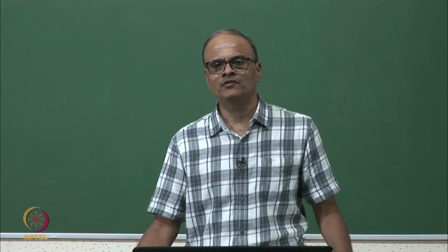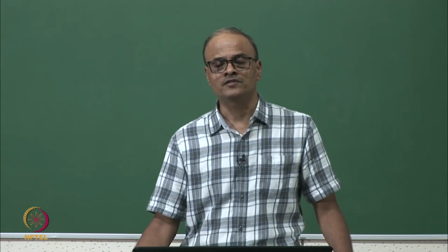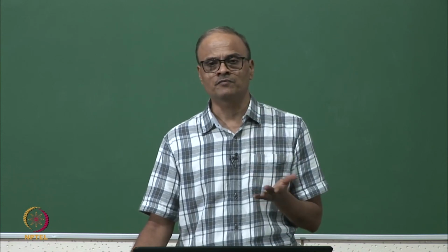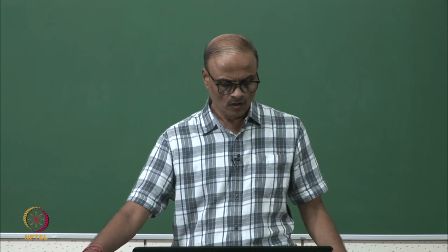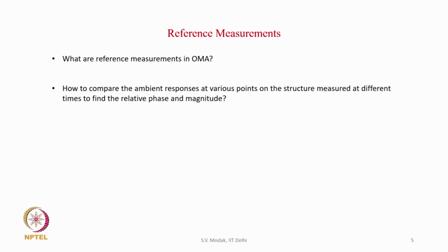One of the differences between the operational analysis and the experimental analysis is the fact that in operational analysis reference measurements are taken. So, let us try to understand what reference measurements are and why they are taken in operational modal analysis. So, the question is how to compare the ambient responses at various points on the structure measured at different times to find the relative phase and magnitude.